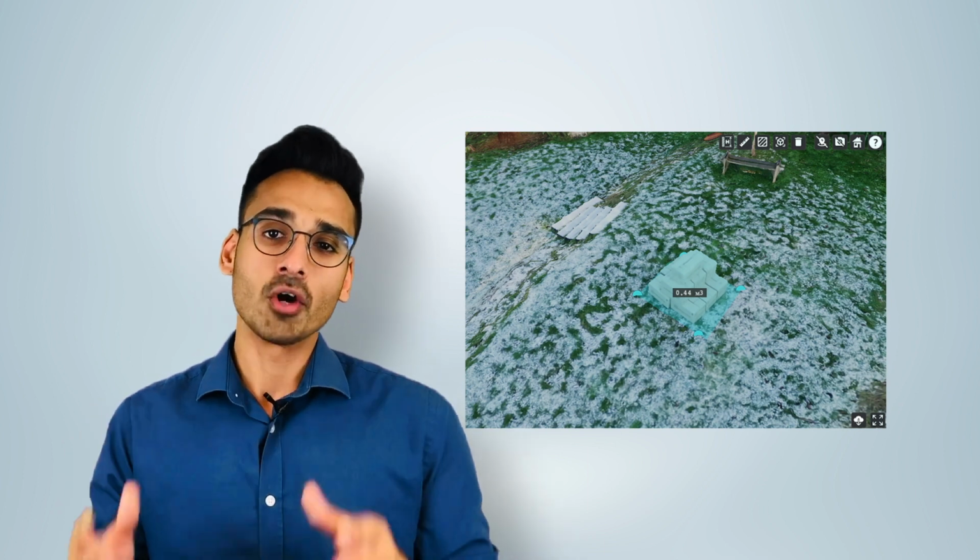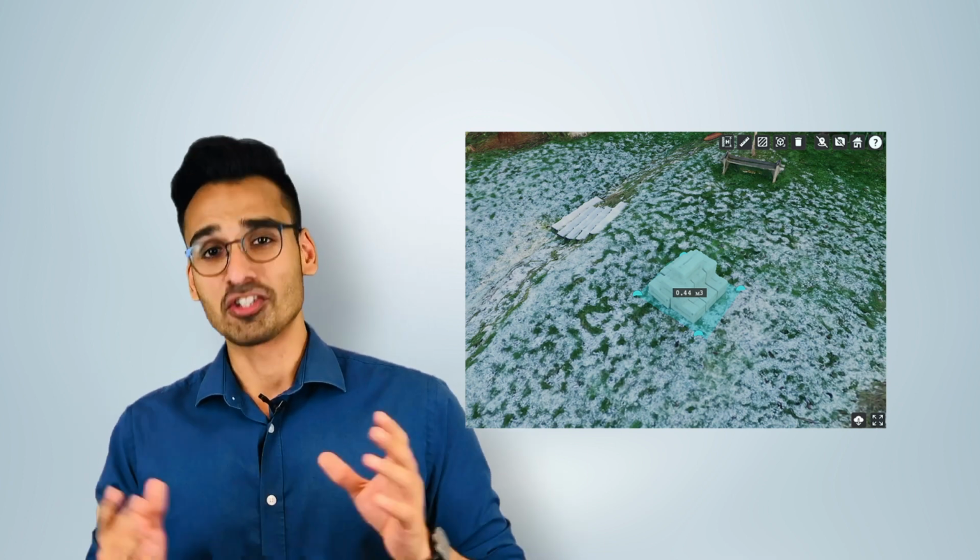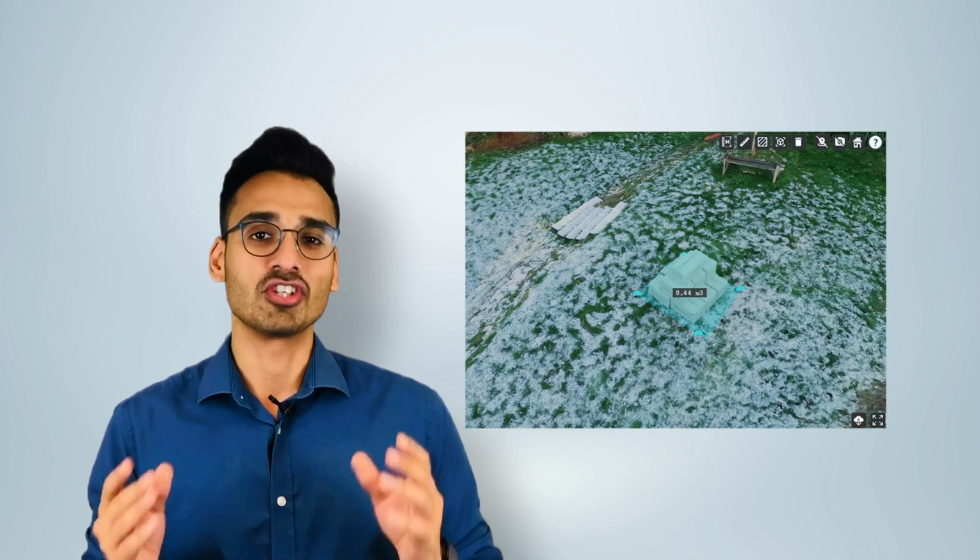We have done certain experiments in the past where we have captured stockpiles, and we know that the accuracy of the stockpile measurement is very much dependent on the GSD used to capture those stockpiles. Therefore GSD is really important with respect to a certain application, and you need to always take that into account.